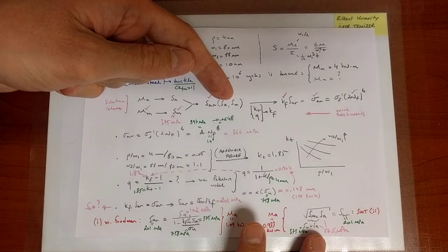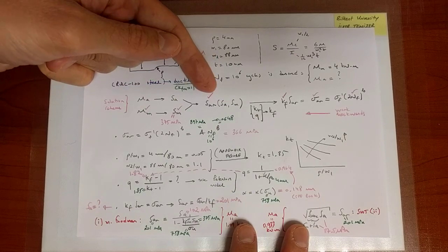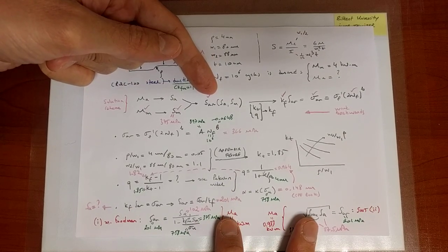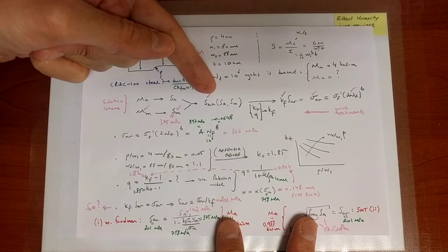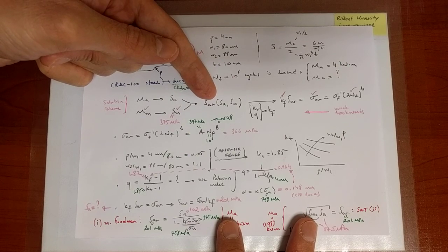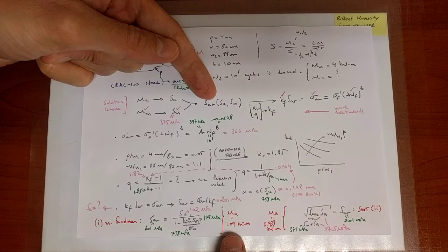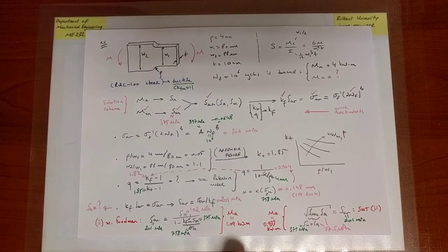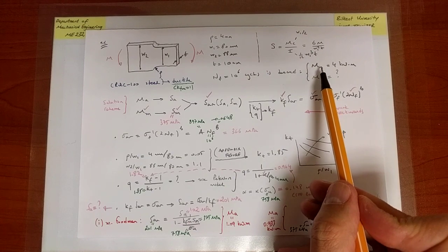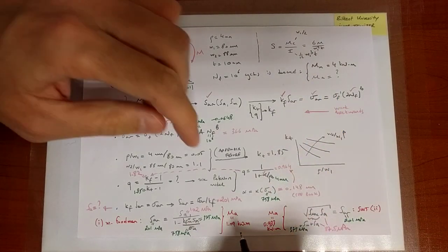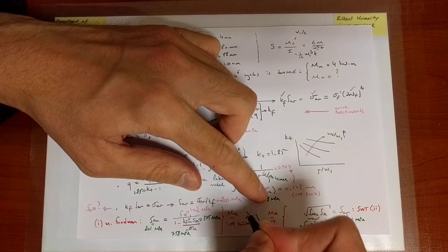But here we've made a choice between the two models for mapping alternating and mean to a completely reversed equivalent alternating nominal stress. And that choice, notice, although the functions look very different, they both ultimately predict that the maximum alternating bending moment you can apply in the presence of such a mean value is of the order of 1 kilonewton meters.